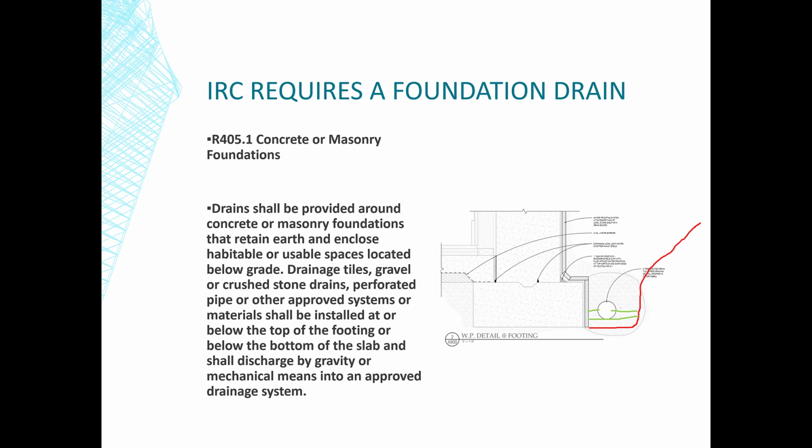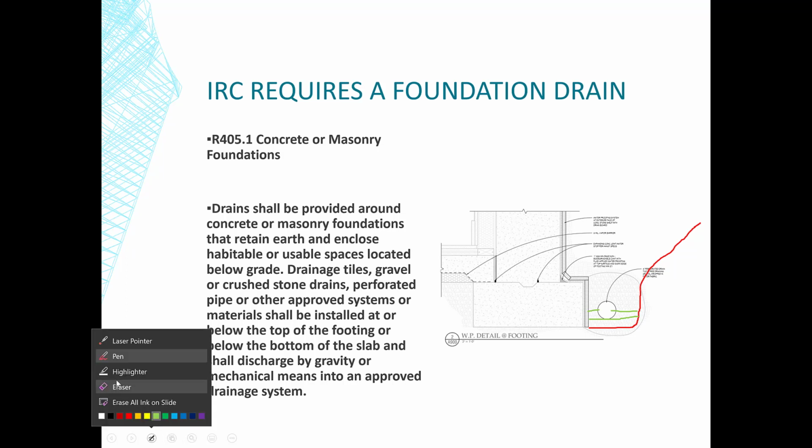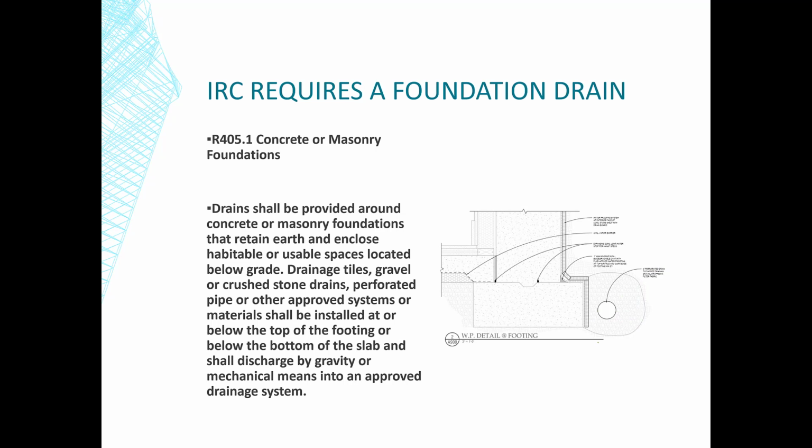Use the first level to set the grade, second level to hold it in place. And then you're just backfilling away. And then let's see if I can learn how to clear this. Then the fabric is going to wrap itself around, right? And then you continue to backfill.